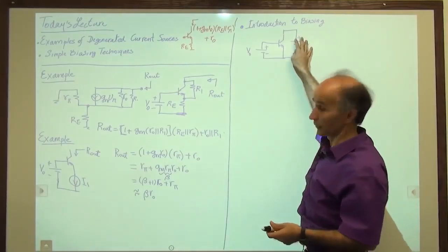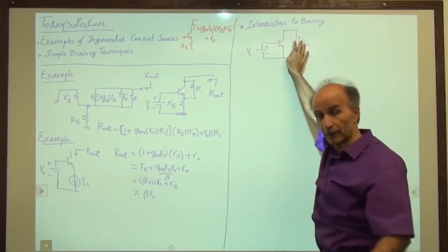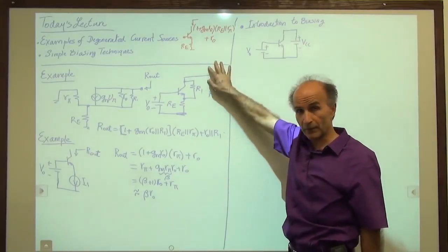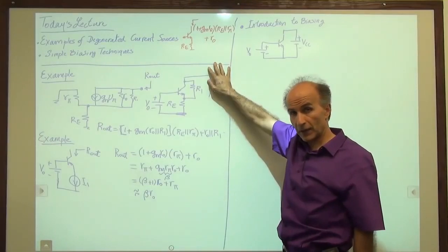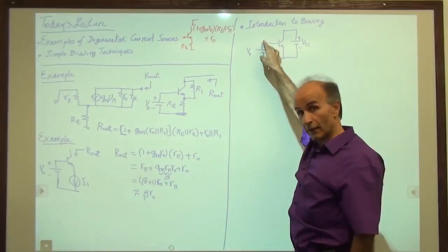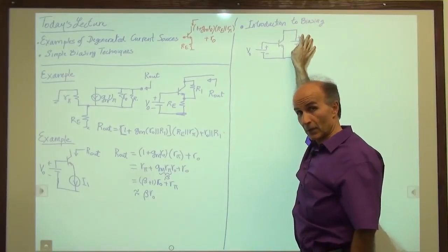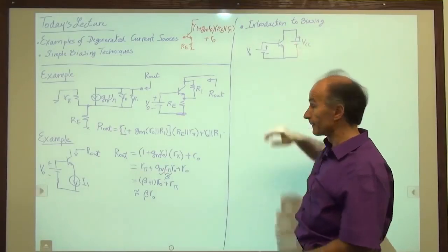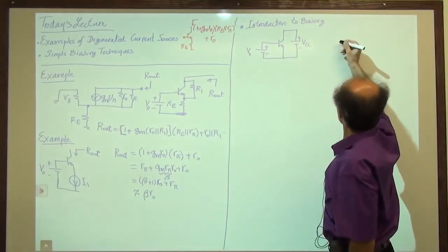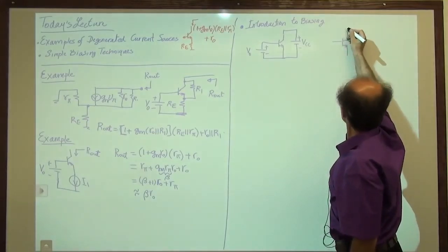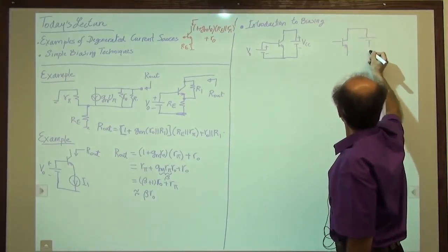Let's say this is the battery. This battery feeds everything. It feeds the collector current, it feeds other parts of the system. So the question is, can I generate the voltage that I need here from this battery? And if you remember that we have resistive dividers, yes, why not? So let's do it this way. We draw the transistor again. Here's our battery.